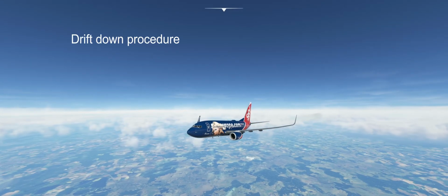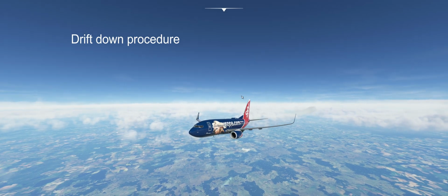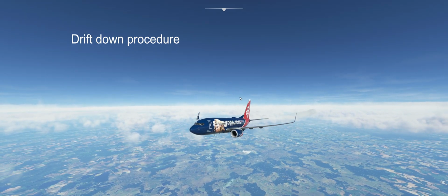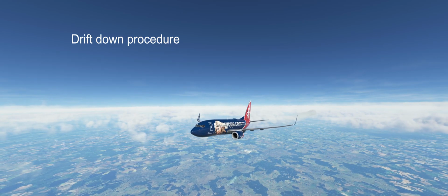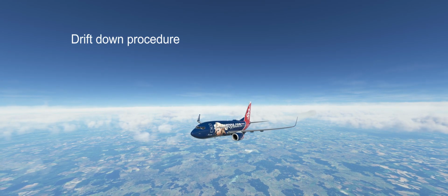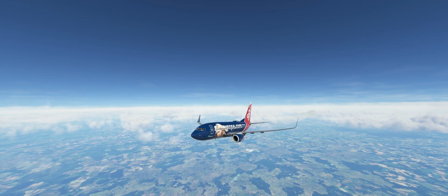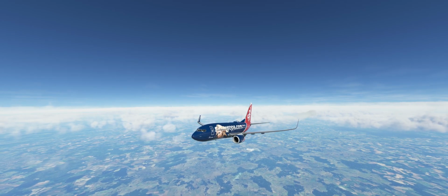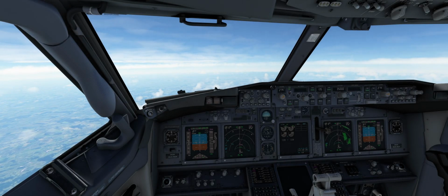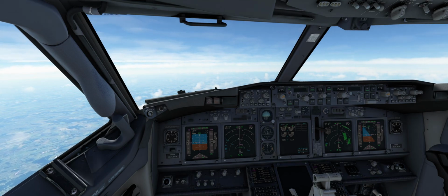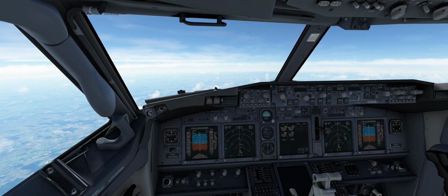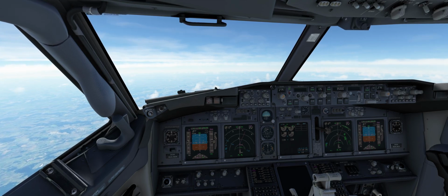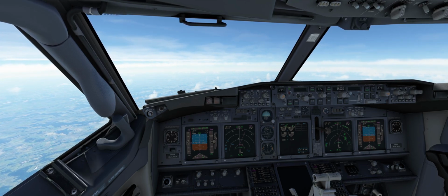Hello friends, good day. Welcome to another educational video, and now we are going to discuss what is the driftdown procedure. So driftdown procedure is basically the procedure which the flight crews are using while they are cruising and they suddenly lose the engine.